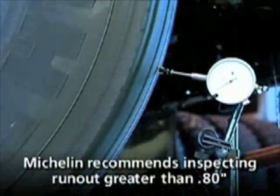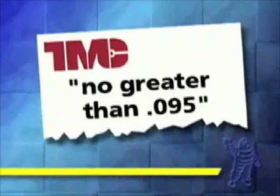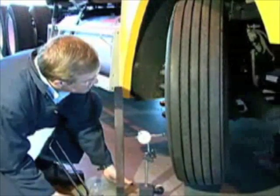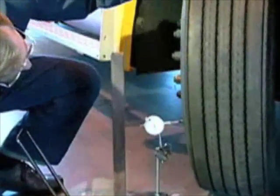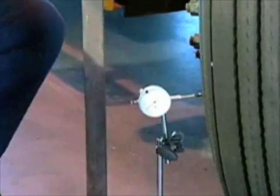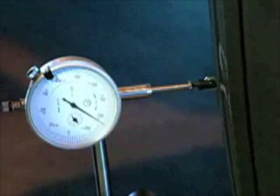Any radial runout found greater than 80 thousandths needs to be further inspected. The Maintenance Council, TMC, currently recommends no greater than 95 thousandths of an inch. Now position the dial indicator perpendicular to the sidewall as close as possible to the center of the sidewall area without hitting any lettering. Slowly rotate the tire a few revolutions to obtain the high and low readings.